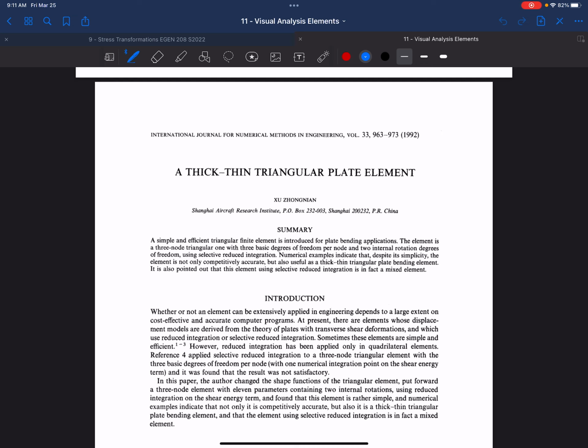They just added a new 3D FEM module for footings. Oh, they did? Yeah, so maybe I haven't tried it. I usually would do footings in Visual Analysis, and then do a plate model with the columns coming down. Then you get your forces out of the model, the moments and shears out of the footings, and you would just go back and design it by hand.